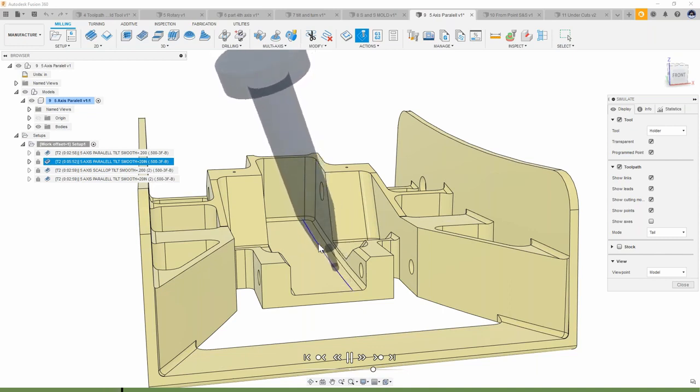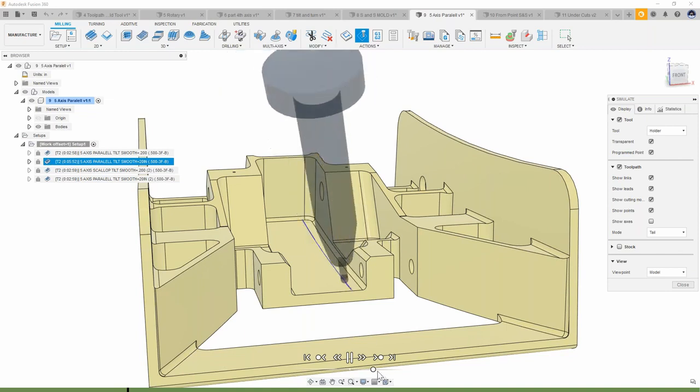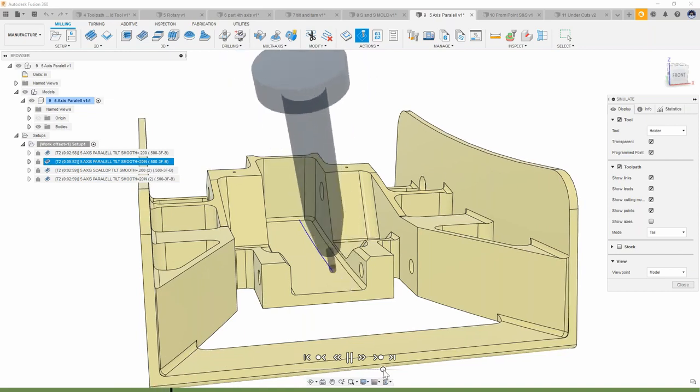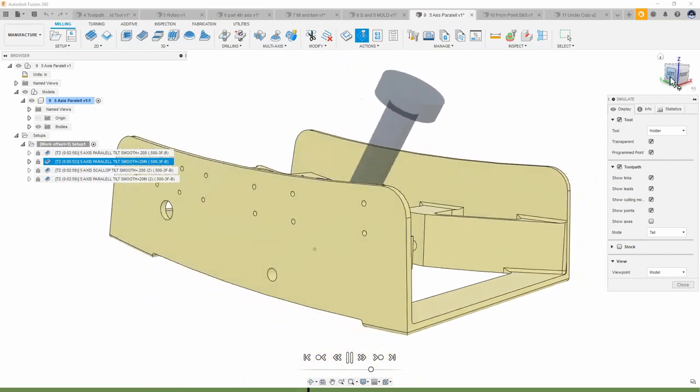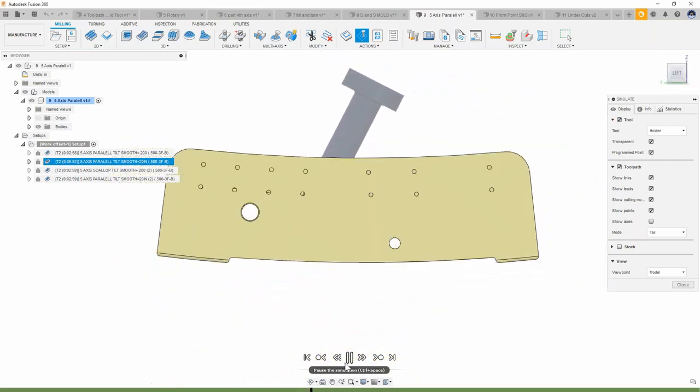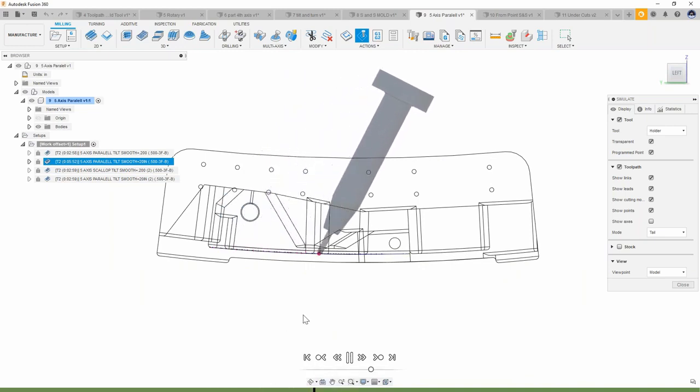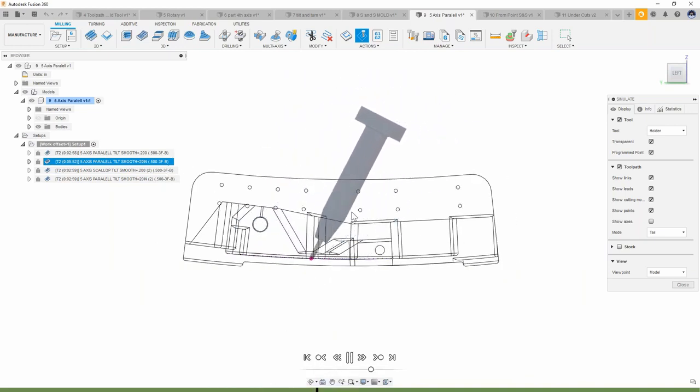So if we are doing a toolpath 5-axis here, and we have to do this to correct the motion, what I would like to see is what this toolpath does in the middle here. And if we look at this, I'm going to go to the side, and I'll hit Control-7 to do a wireframe. We can see that once it reaches the middle there, where we don't have any collisions on either side, it actually finds a tool orientation where we could machine this from, and it locks 3+2.